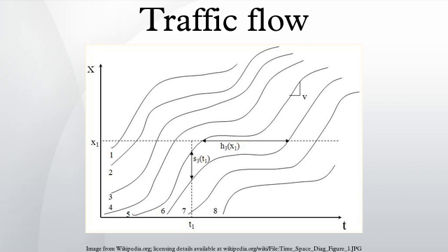Overview: traffic phenomena are complex and nonlinear, depending on the interactions of a large number of vehicles. Due to the individual reactions of human drivers, vehicles do not interact simply following the laws of mechanics, but rather show phenomena of cluster formation and shock wave propagation, both forward and backward, depending on vehicle density in a given area. Some mathematical models in traffic flow make use of a vertical queue assumption, where the vehicles along a congested link do not spill back along the length of the link.